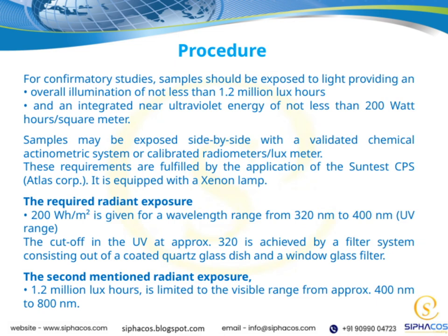This means that the total amount of light intensity over the exposure period needs to reach that threshold to simulate real-world conditions accurately. In addition, the samples should receive an integrated near-ultraviolet energy of no less than 200 watt-hours per square meter. This UV component is crucial because UV radiation can significantly affect the material's stability and performance.